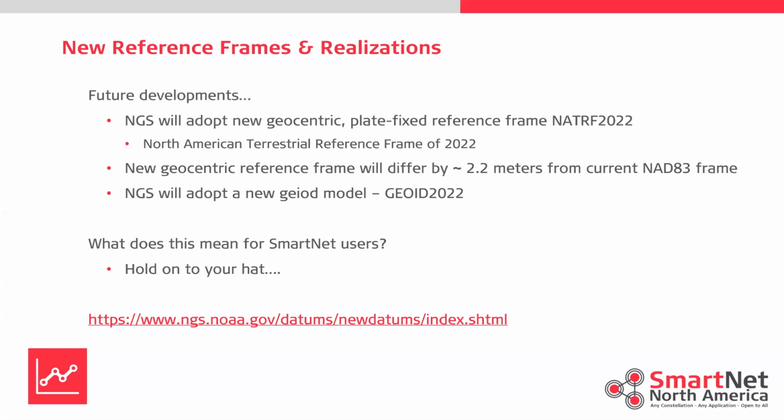So this is just a realization update to the existing reference frame, but NGS is adopting a completely new reference frame in roughly 2022. This is a geocentric plate fixed reference frame called NATRF2022. That's the North American Terrestrial Reference Frame of 2022. With it being now geocentric, it will differ from the current NAD83 frame by about 2.2 meters. But that's a big difference, Tyler.